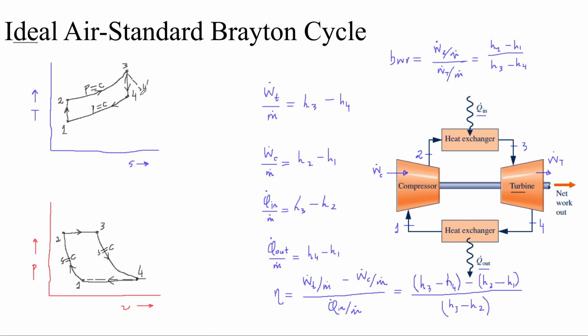And now we cannot decrease this entropy in a way such that the process is reversible, such that the process does not have any effect on the system and the surroundings as well. So instead, we need to go for a process in which entropy doesn't change, so we can go back onto it and make this process reversible as well. That's the reason why we have the isentropic process here for the ideal Brayton cycle.